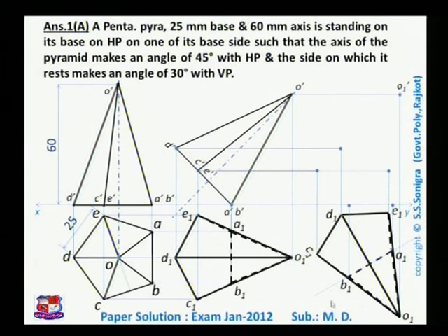Now if we look from this direction, this side, this point O dash to this, that is B. OB is towards us. You can see here OB is towards us. If we look from this direction, OB is towards us. Hence O1 dash, B1 dash would be fully visible. So join them with a full line like this. It's a straight line.